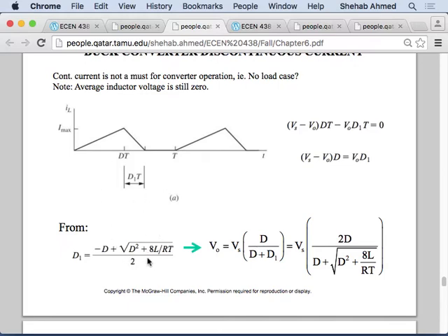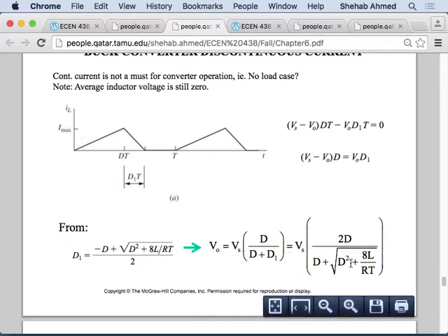So in this discontinuous mode, it's not simple anymore. Because when you change the load and you change your control, the way that your power supply will respond is not linear anymore. You used to change duty ratio and you saw the output voltage increasing. V output was equal to V input times duty ratio. Increase duty ratio, output is increasing. Decrease duty ratio, output is decreasing. But here, what's going on? It's a different curve. It's a curved relationship. It's not a linear relationship anymore in this case.